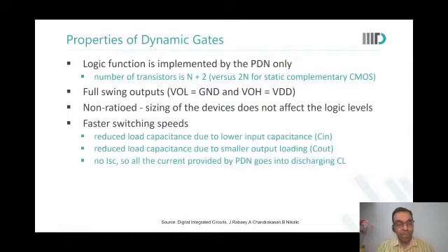What also has happened, we discussed this in the last class. We've reduced the capacitance. Which capacitances have we reduced? The input, all the PMOS ones. So we reduce the input capacitances because the signals no longer need to go to the PMOS. If I make a dynamic inverter, the PMOS would have a clock on it, there would be one NMOS with a clock on it, and then the other NMOS.